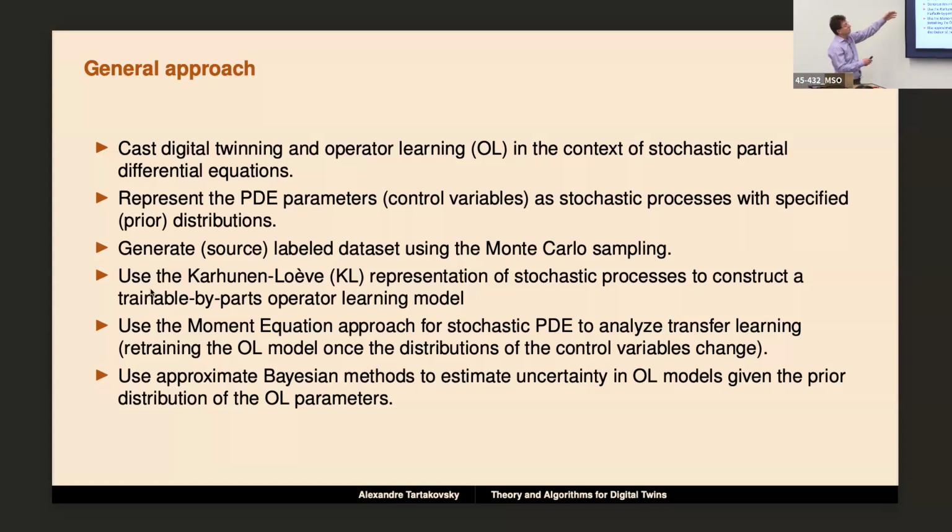Of course, this makes the governing equation stochastic. Then we generate a labeled data set for training the digital twin using Monte Carlo sampling of our stochastic PDE solution. Then we use the Karhunen-Loève representation of the stochastic processes to construct, as we will show, an operator learning model that can be trained by parts.